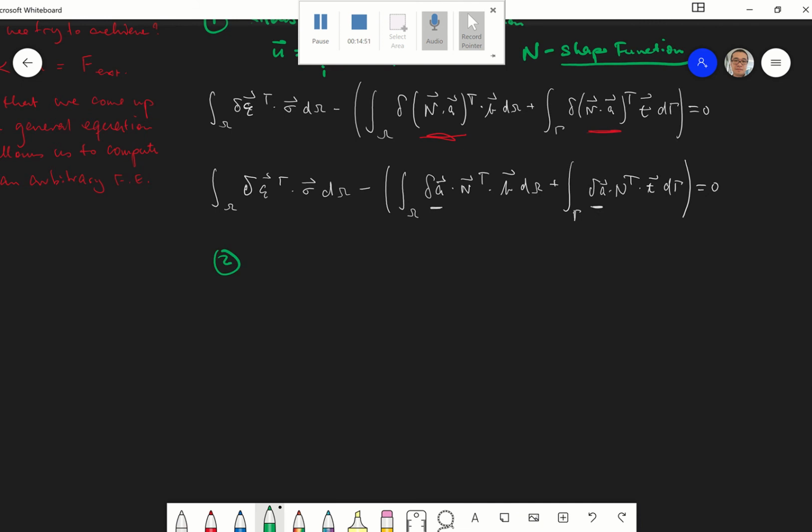We have an expression for strain, where the epsilon equals a matrix S times the shape function N times A, which we can group the S dot N together later and get a new matrix B dot A. Right? The meaning of that, and how we calculate these things, will appear a bit later.